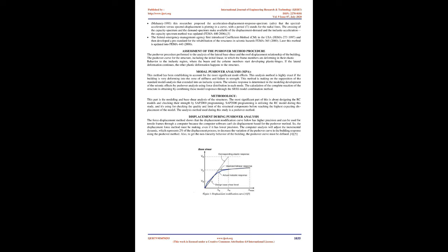There are two types of steel bracing, concentric steel bracing and eccentric steel bracing. Therefore, this research is concerned with the concentric steel bracing system. There are two types of concentric bracing system: the concentrically braced frame, CBF, and the special concentrically braced frame, SCBF. The difference between these two concentric systems is that SCBF can absorb more deformation in tension and compression than CBF. SCBF is used to give soft story stability against the seismic loads acting on the building.